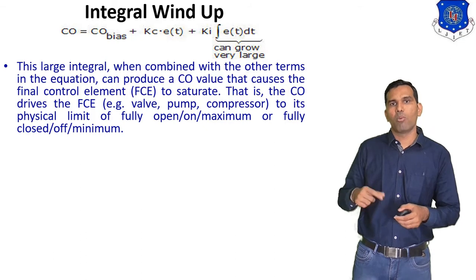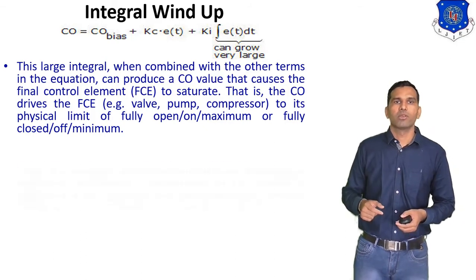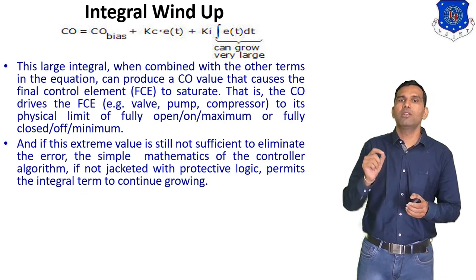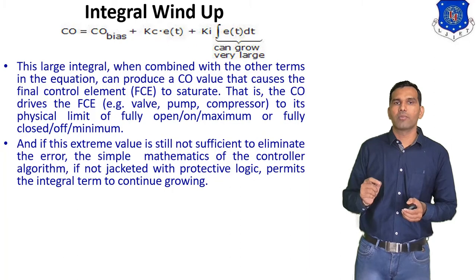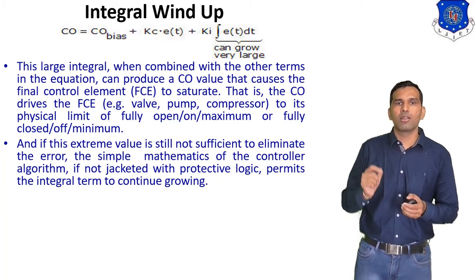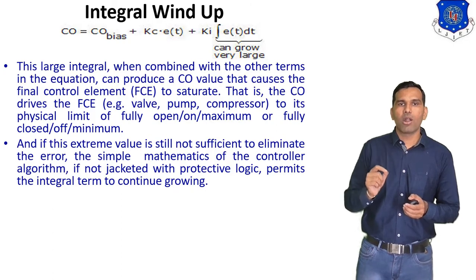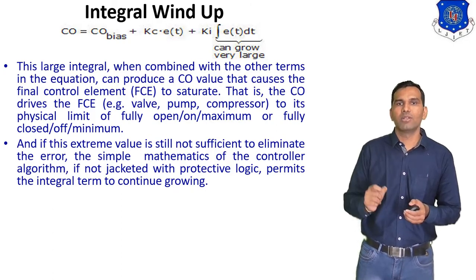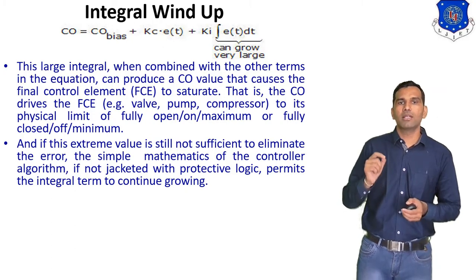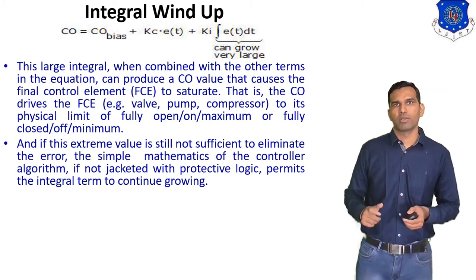And if this extreme value is still not sufficient to eliminate the error, the simple mathematics of the controller algorithm, if not jacketed with protective logic, permits the integral term to continue growing.